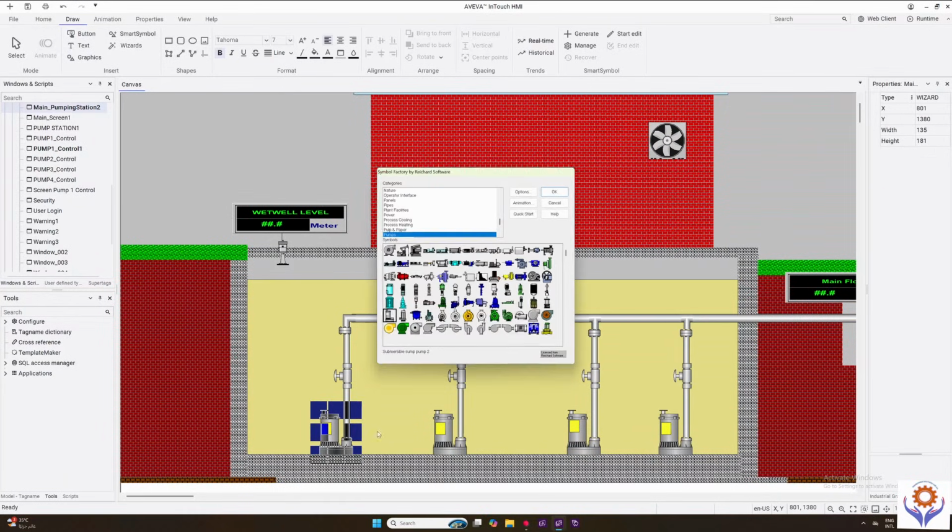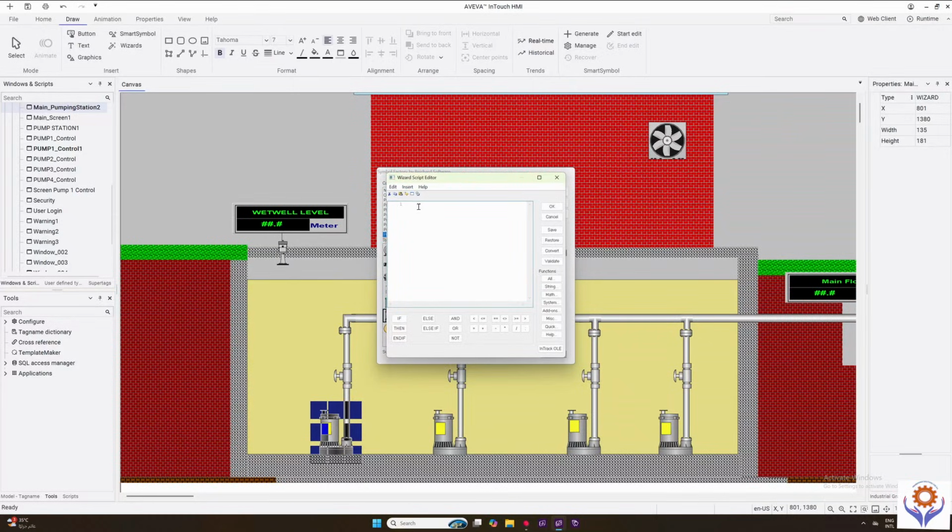So if you see, there are three options to close. Otherwise you can utilize it directly with the fourth option in the property itself. See, if I look here at the pump, I can select. See here I did not select anything. After this I need to link the pop-up. For that I am going to use show, and I can give the window name directly. This means if I click the pump, it will directly link with the pop-up, and it will show you the pop-up screen directly. From here you can search the window name directly or copy paste.